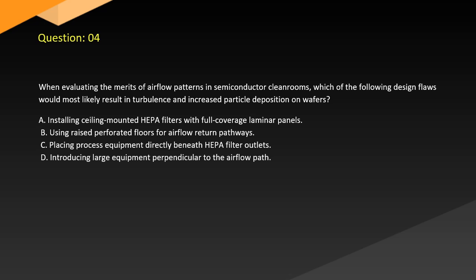Question 4. When evaluating the merits of airflow patterns in semiconductor cleanrooms, which of the following design flaws would most likely result in turbulence and increased particle deposition on wafers? A. Installing ceiling-mounted HEPA filters with full coverage laminar panels. B. Using raised perforated floors for airflow return pathways. C. Placing process equipment directly beneath HEPA filter outlets. D. Introducing large equipment perpendicular to the airflow path.